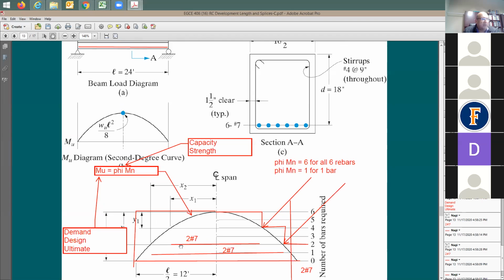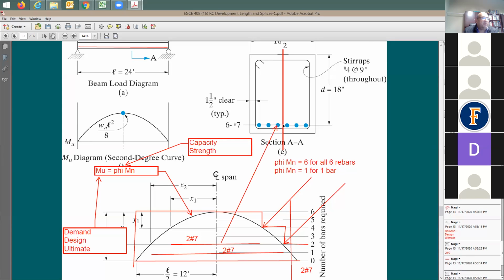Now, someone's going to say, why didn't you say 3 rebars? I'm going to say now, you need to keep symmetry, right? You need to keep the symmetry when you're curtailing the rebars. So you're going to say, where's the first 2 rebars? This 2 rebars, right? Where are these? And say, this rebar is giving this 2, right? So at a certain point, I can stop 2. How about this, the bottom 2?